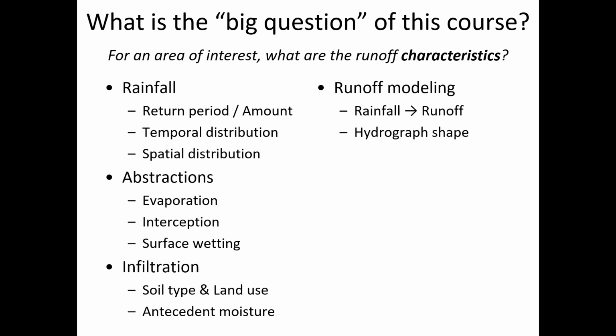We have to understand how quickly the water is going to be coming in, because dams, of course, are in part designed to release a certain quantity of water, and most dams will have a primary route that the water is going out. Maybe if it's an electricity generating dam, it will be through a penstock that is routed through turbines, but then there may be an emergency overflow and then a separate, not an overflow spillway, but sometimes discharge structures that don't necessarily have power attached, but it saves you from the surface scour that would occur if you're using the overflow spillways.